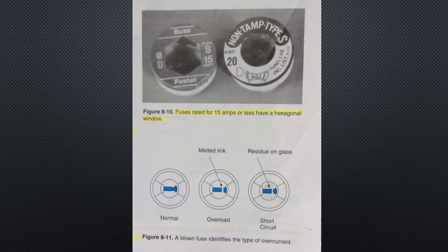This potentially dangerous oversizing problem is eliminated by using a type S fuse, which uses a screw shell adapter. The type S fuses must be used on all new installations and for replacement installations. There are 3 classifications of type S fuses with specific adapters based on their ampere ratings of 0 to 15 amps, 16 to 20 amps, and 21 to 30 amps.